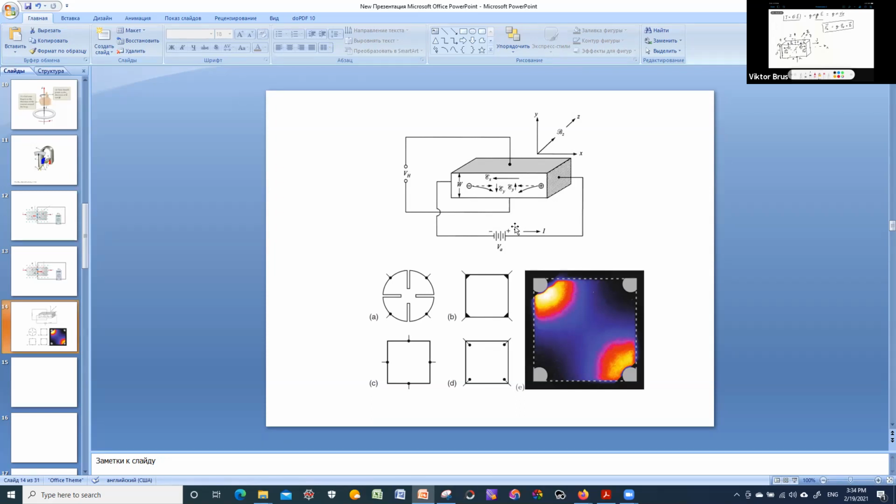However, very often we deal with thin films, and in that case it is not possible to make bulk samples, specifically when we deal with graphene, which is known to be a monoatomic layer. So by definition it cannot be three-dimensional, it's two-dimensional. In that case, a different approach called the Van der Pauw technique allows us to make 4 contacts on these films.